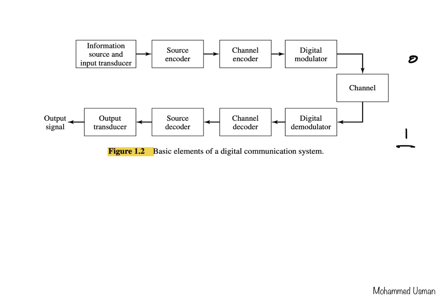So even in a digital communication system, the signal that propagates through the physical channel is still an analog signal. But we do all the processing in the digital domain, and that digital signal modulates the analog carrier, and we call that digital modulation because the information signal that modulates the carrier is a digital signal.